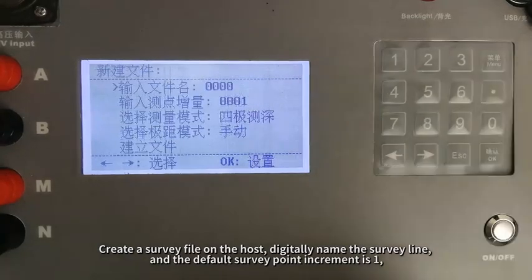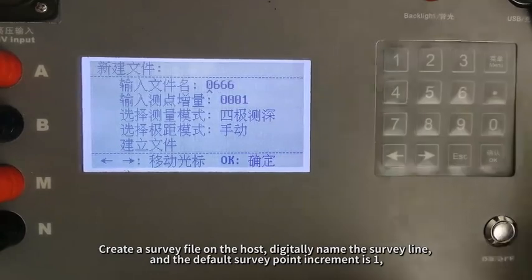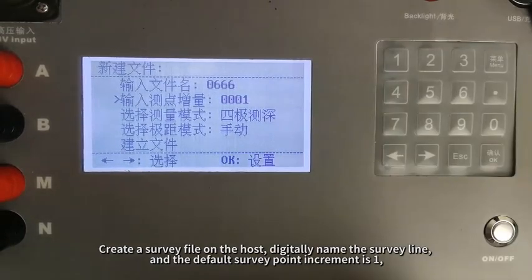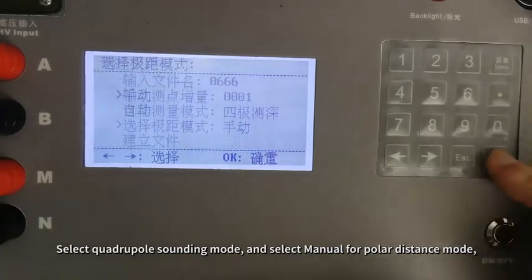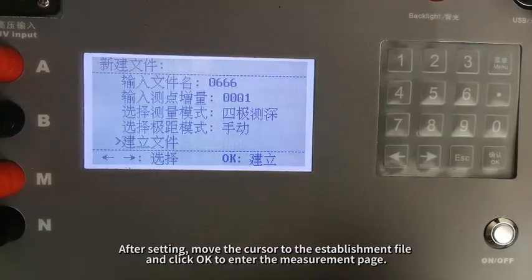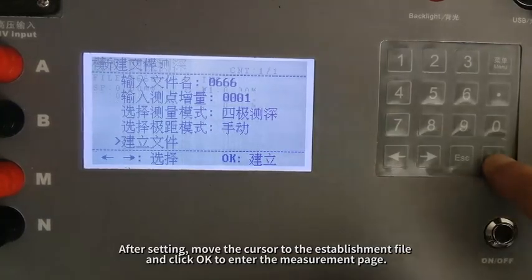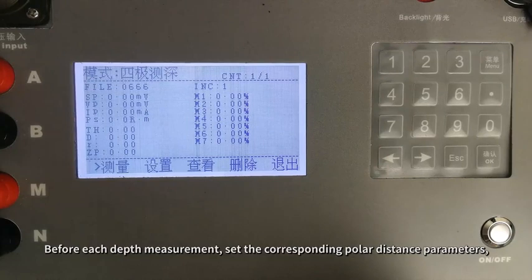Create a survey file on the host, digitally name the survey line, and the default survey point increment is 1. Select quadrupole sounding mode, and select manual for polar distance mode. After setting, move the cursor to the establishment file and click OK to enter the measurement page. Before each depth measurement, set the corresponding polar distance parameters.